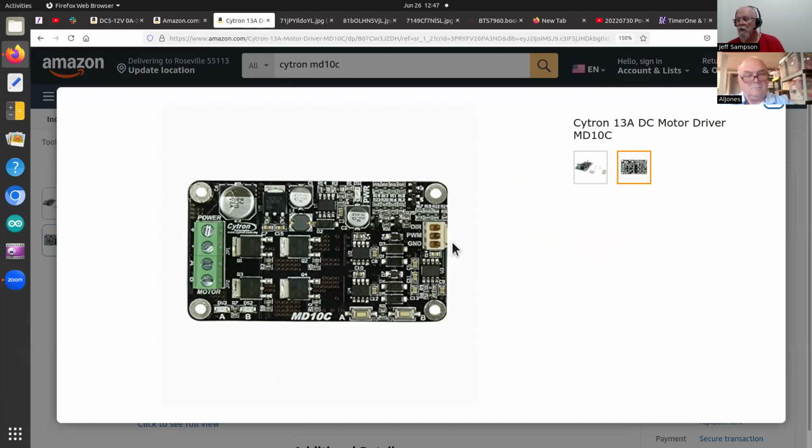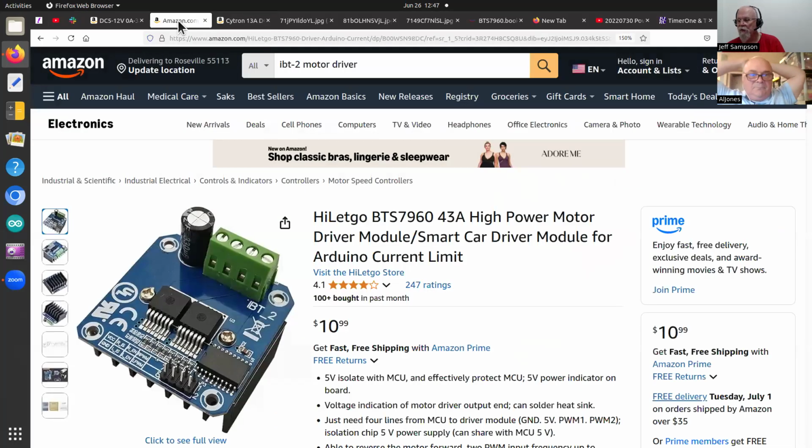And this one, you create a PWM on the processor, and you've got just the direction bit. You can set it high or set it low to make it go forwards and make it go backwards. So that's really the 3 different types of stuff. That's what I have. Now, did I skip over this board?